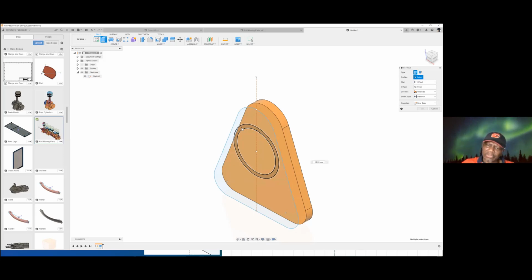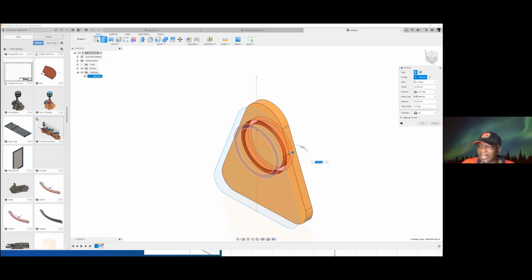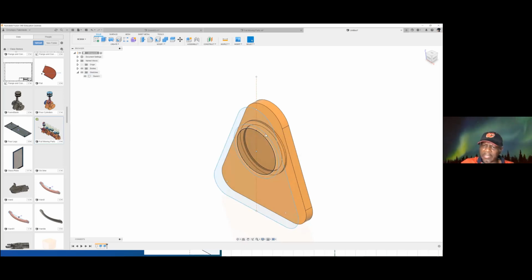And we're creating the extrusion there, and that extrusion would now start at an offset of 10, and it will be going through a distance of 2, and it will join the original thing. So you can see this extrusion now is an offset of 10 and it has joined.